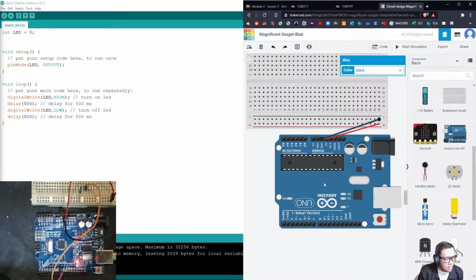If you look at our Arduino, there are currently multiple ground pins that you can use. These ground pins, which have negative polarity, can be interchangeable. So you can use any one of the three ground pins that you can find in the Arduino Uno. You may use this, or you may use the two ground pins here, it would be the same. A ground pin is provided here for convenience sake only.